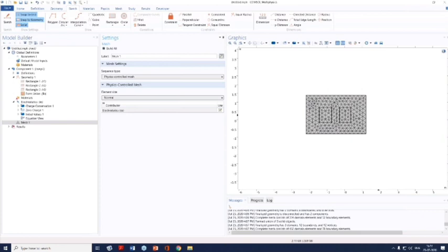In that case, you can create your circuit interface wherein the lumped elements can be added, create your 3D capacitor model which is going to be studied, and then couple this lumped electrical circuit to your capacitor. The same way you can provide excitation to any of your electrical machines, or take output across any lumped circuit for your electrical machines, just to give you an example.